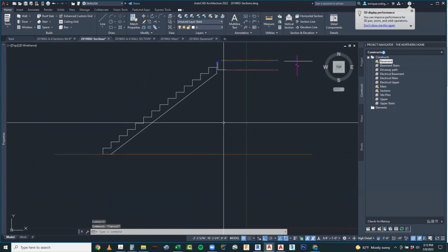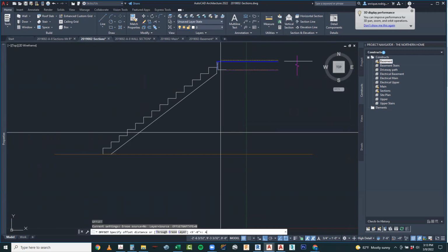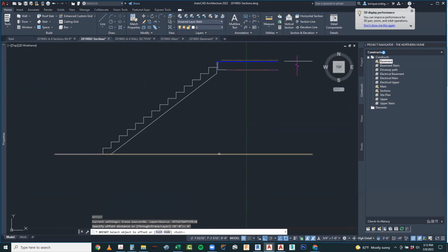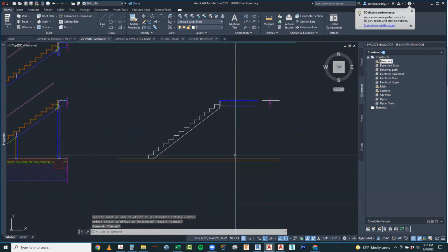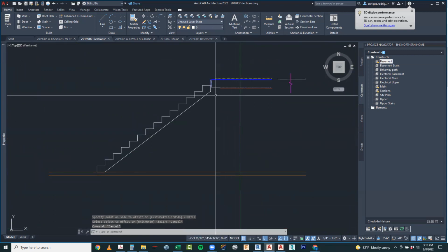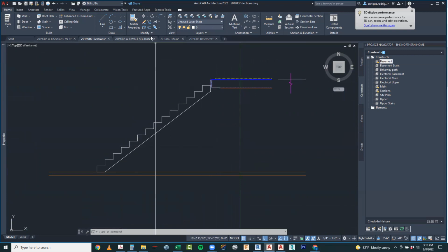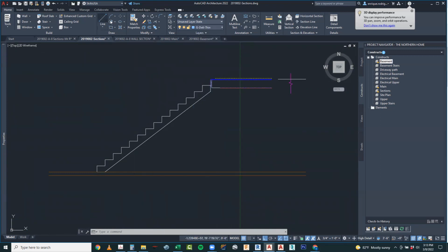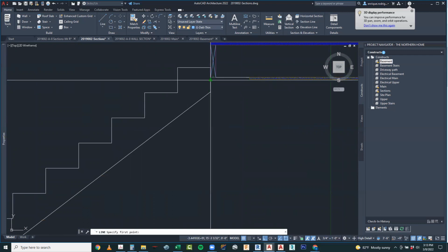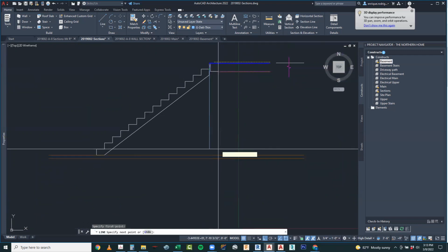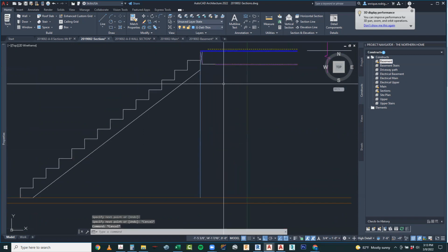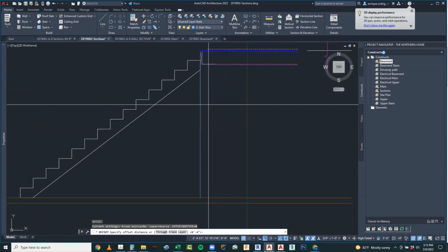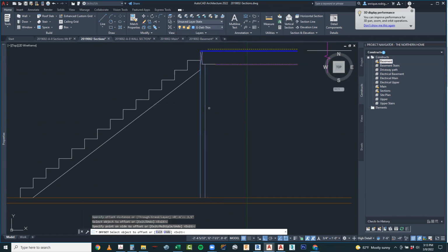Now its colors are a little bit different. And just like we did in our wall section, we know that it's a 4-inch thick slab going across like that. The next thing we're going to do is draw our 2x4 wall. Again, this is not in section, so I'm going to use G detail thin. And I'm going to draw a line from here that represents the structure. And I'm going to offset that 3.5 inches, which represents a 2x4 wall.